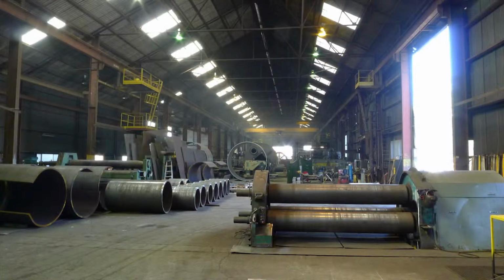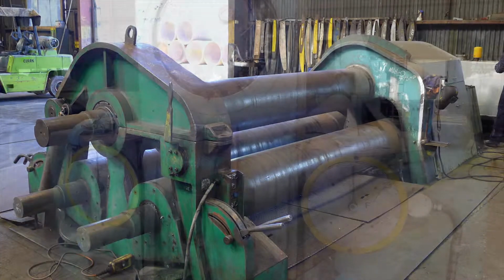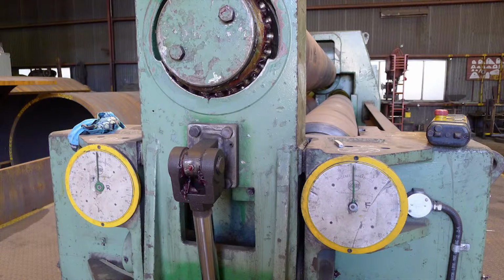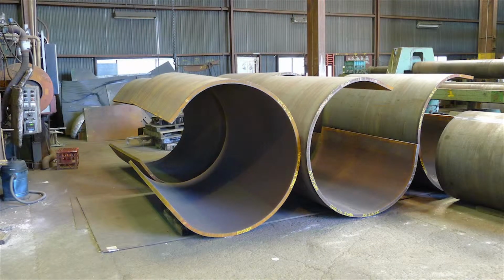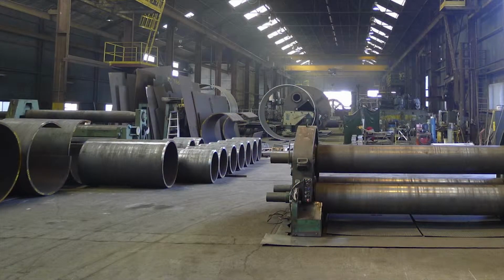In industry, there are some similarities and differences. These pyramid rollers at ER Curtin are similar to those found in schools, except that they can roll plate steel sheets 3 metres wide and up to 50mm thick. All of the cylindrical sections found in the factory as part of the current build have been formed on this machine. ER Curtin does not use pan brakes as they are specifically designed for the bending of sheet metals.